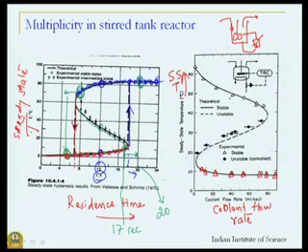If we start the experiment the other way round, that we keep a very low coolant flow rate, then we may expect temperatures to be high, and this is what we can expect. So, very high temperature and then temperature progressively decreases as we are increasing the coolant flow rate. But if you increase the coolant flow rate beyond a certain value, we now actually see a very low temperature, or in other words the same hysteresis effect is seen over here as well.